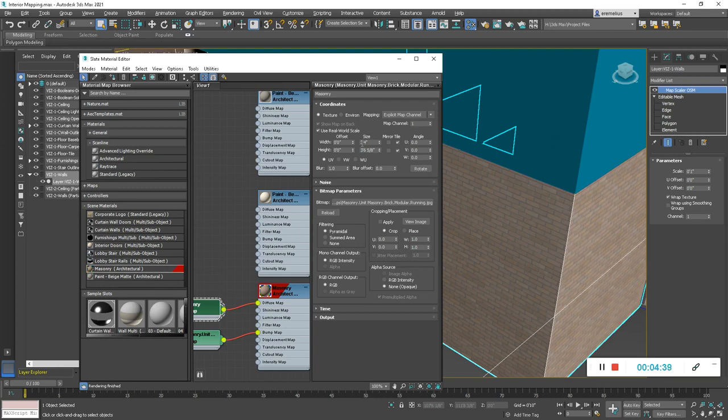If you remember, the reason, as they talked about early on, is how it worked with the courses of the bricks. They showed, at the very beginning of the chapter on page 7-15, that 11 inches times 5 in the U direction equals 4'7", and 4 inches times 16 in the V direction is 5'4". In this case, the U direction is the same as X, and the V direction is the same as Y. So let's change these to be 4'7" and 5'4".